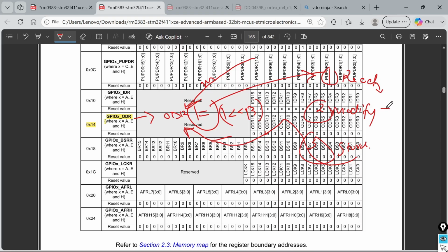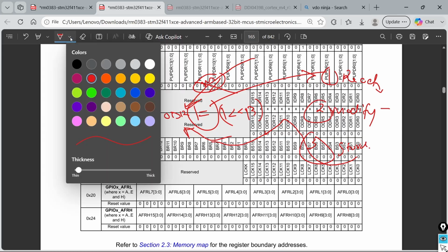You modify it and then you store your modified value. Here you override this M. It's like M was never written in the first place. You can see this is your typical race condition, where the resource was shared between an interrupt and a normal thread.